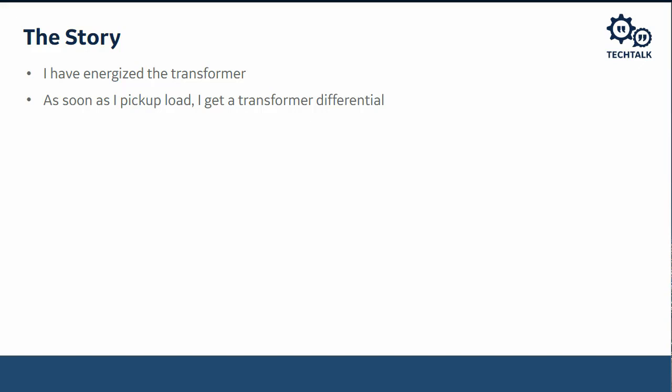Well, at this point, we can't figure it out, right? At this point, I don't have enough information to know what's unique about this transformer that has the problem. And for that matter, two transformers, they're the same size. Same protective relay on both transformers, same wiring, same nameplate information. So there's nothing that I can do. Something has to be unique, either in the relay or the transformer, because it's tripping as soon as they pick up load on one of the relays, but not the other one.